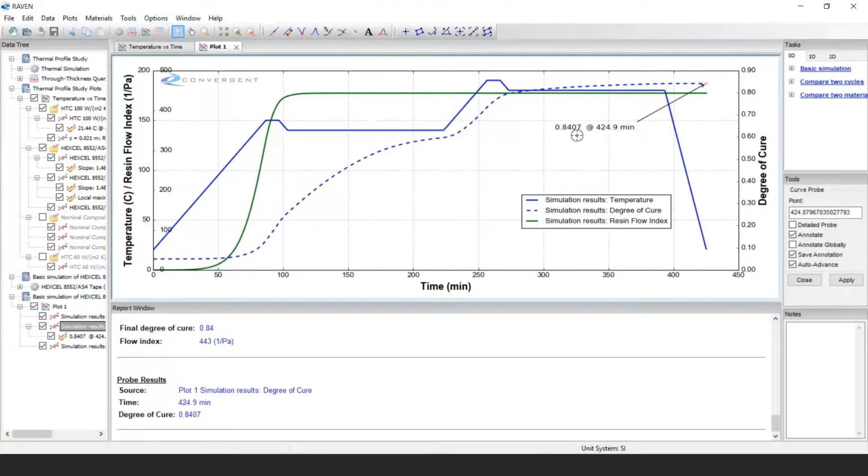That's just not often specified within the cure cycles in specifications. They've designed that cycle to ensure that you get to an appropriate degree of cure. And one way that we would approach some problem like that, if you are not beholden to a specification exactly, is to define what is the minimum properties based on degree of cure, and then optimize to at least achieving that as a criterion. Great.